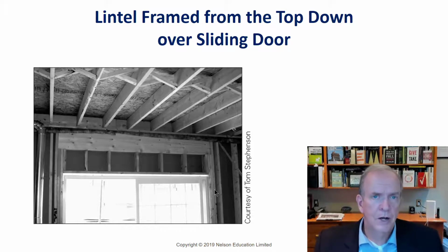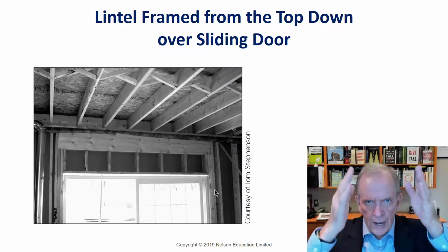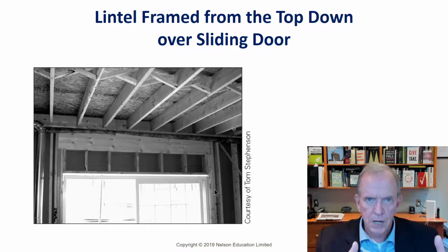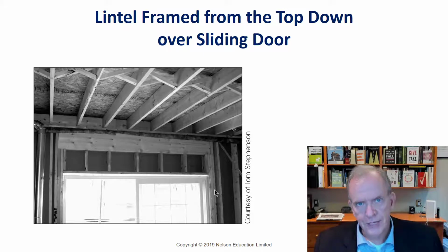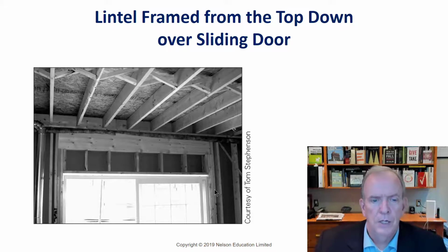If you remember when we started talking about footings and foundations, it's really good to look at the structure and imagine how the loads are being transferred. And if there's any spot where that load is not being picked up, you can infer that there will be some sort of structural issue, some sort of cracking, some sort of sagging. So it's good to sort of follow the loads. So we have this way of transference occurring, and the lintel is placed on the top.